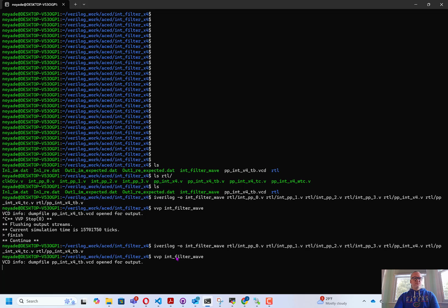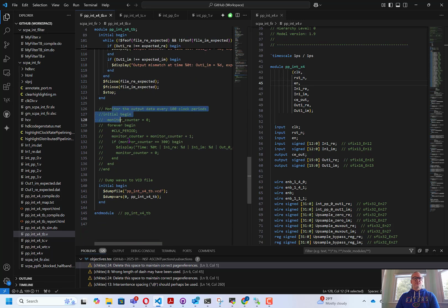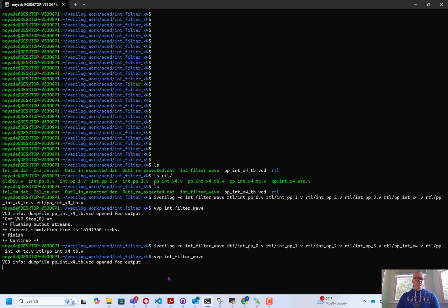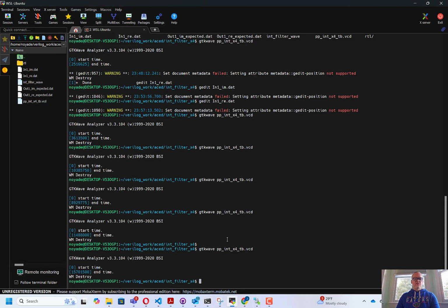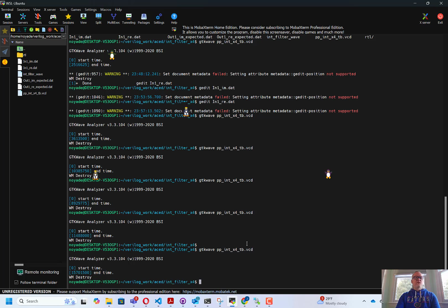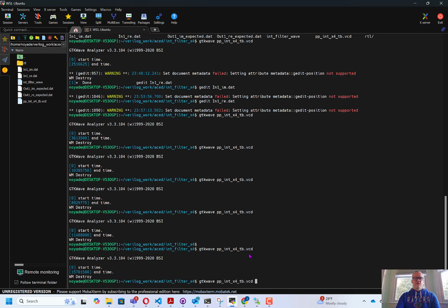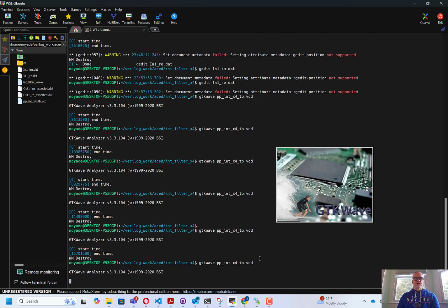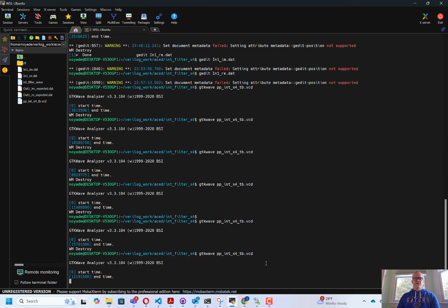And what you'll find when we run the simulation is I've turned off the monitor that would be outputting a display just to make sure that the simulation's running. But if you want, you can re-enable something like that. I'm going to pause the simulation after some period of time. It'll tell you how long it's run. And now we can go to the MobaXterm here, open up Windows Subsystem for Linux and MobaXterm, and this is going to allow us to forward X to the display. So here I'm going to open up GTKWave using the command GTKWave with the waveform file that we create.